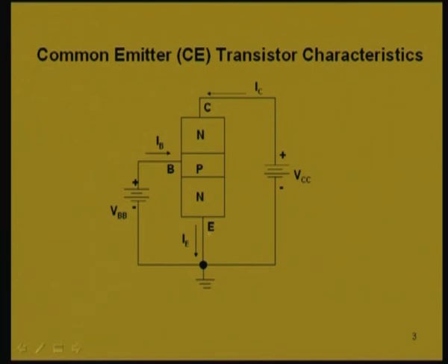If we consider an NPN transistor, the emitter and base are N and P respectively. So, the base, which is P, will have a higher potential than the emitter. VBB is biasing it in the forward direction, and the collector base junction should be reverse biased, which is taken care of by the potential VCC.